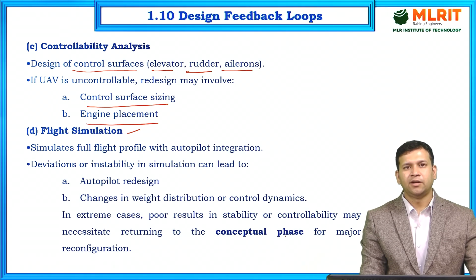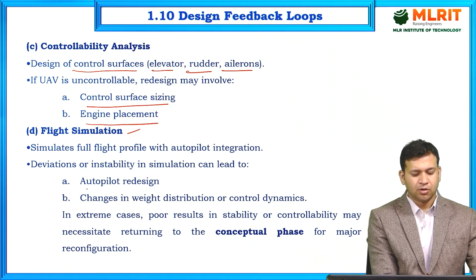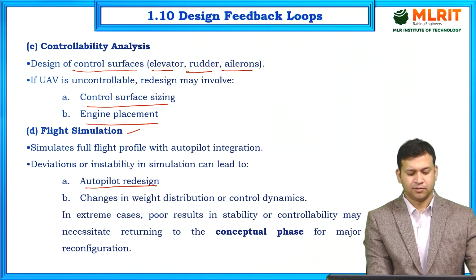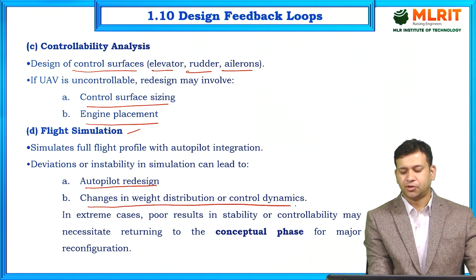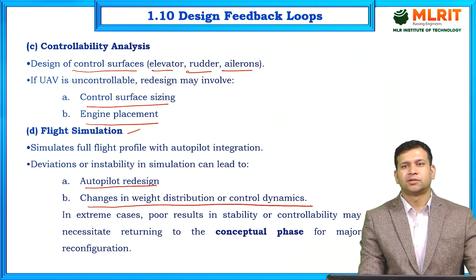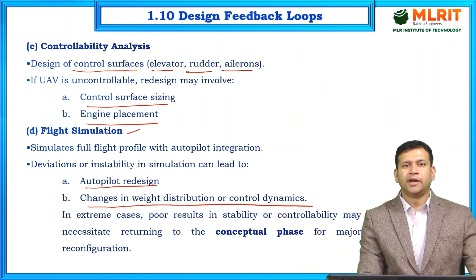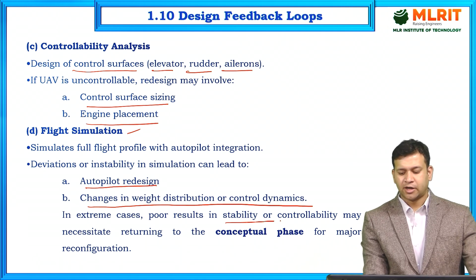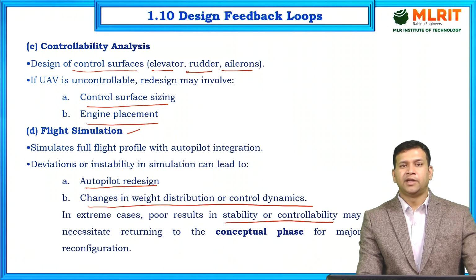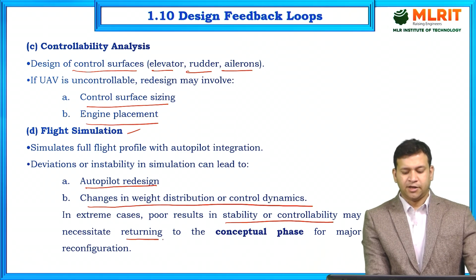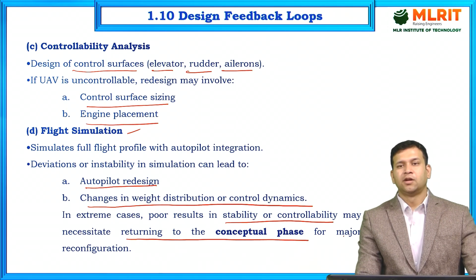Deviations or instability in simulation can lead to autopilot redesign, changes in weight distribution or control dynamics. In extreme cases, poor results in stability or controllability may necessitate returning to the conceptual phase for major reconfiguration.